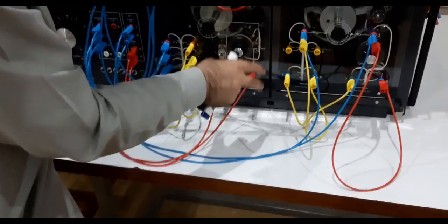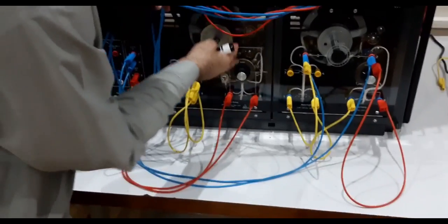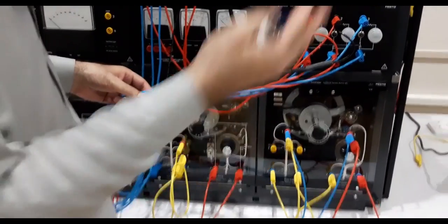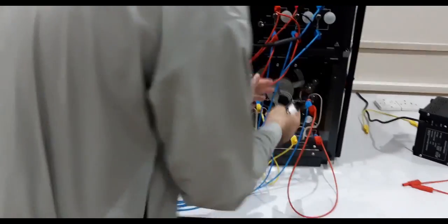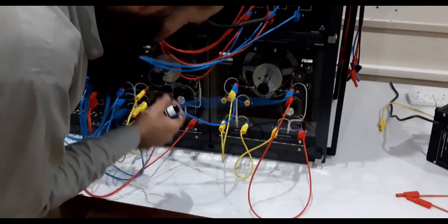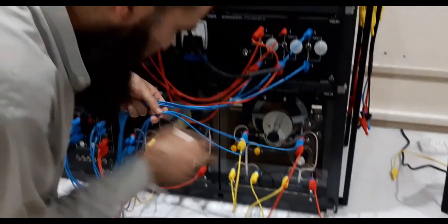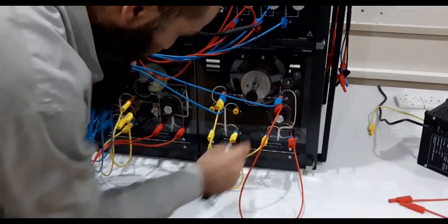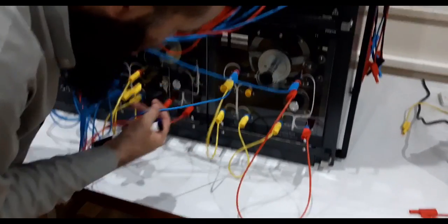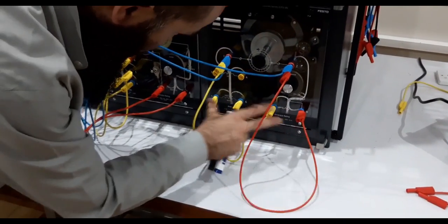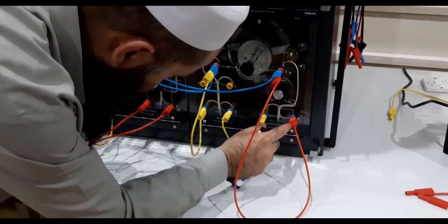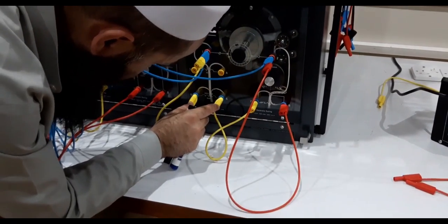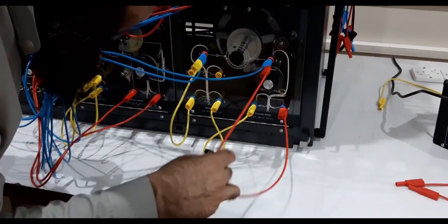Now further, because I mentioned that the synchronous generator should be run by means of a prime mover, and I discussed that the prime mover here is the DC shunt type DC motor. So here this connection is the armature connection, and as one can see here, the field also has a rheostat or a variable resistor connected in series with the winding. So these two are in parallel.